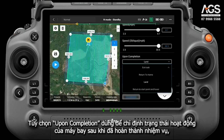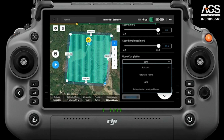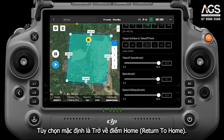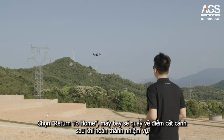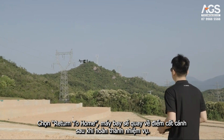Upon completion refers to the flight action performed after the aircraft has completed the operation, which includes 4 options: exit task, return to home, land, return to start point, and hover. The default option is return to home. Select return to home. The aircraft will return to the home point after completing the mission.